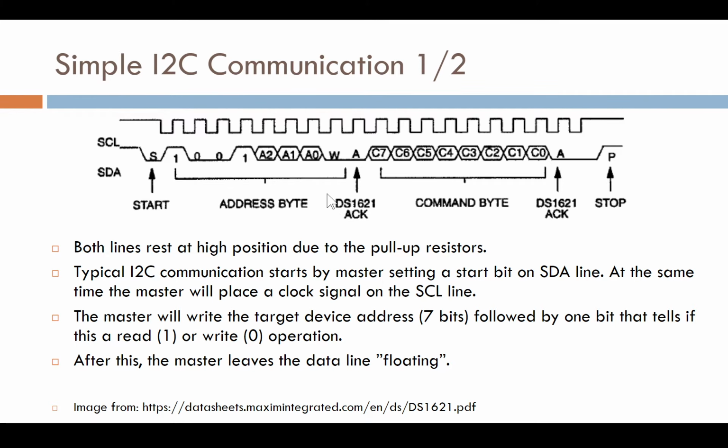This particular example is DS1621, which is an I2C bus temperature sensor. Very popular sensor, for example, inside of your computer. That's most probably the sensor which senses the inside temperature of your computer. Or it could also be glued on the top of your processor, on that processor heatsink, stuck there to measure the processor temperature. Very, very popular component on I2C bus.